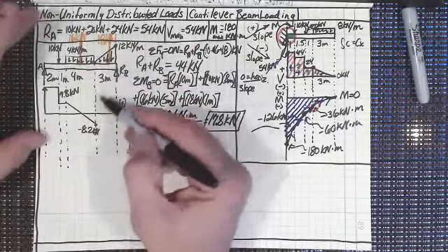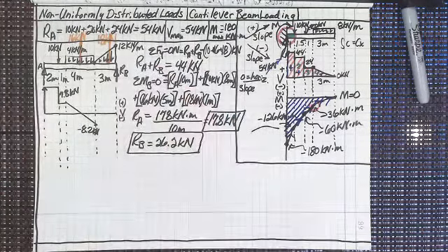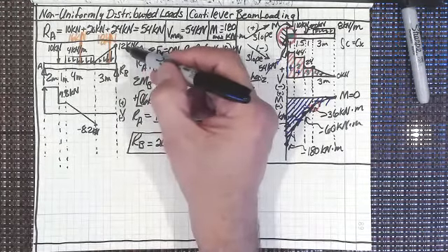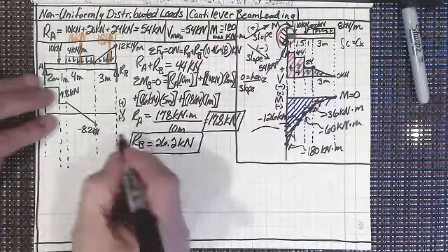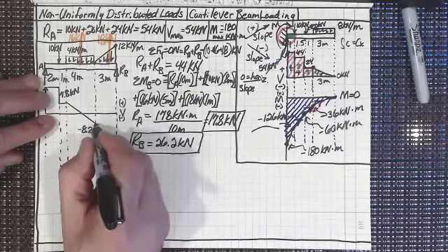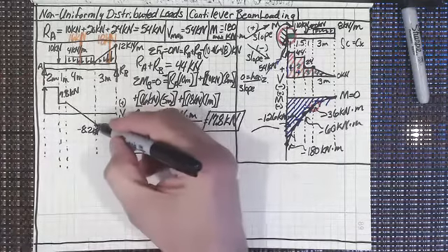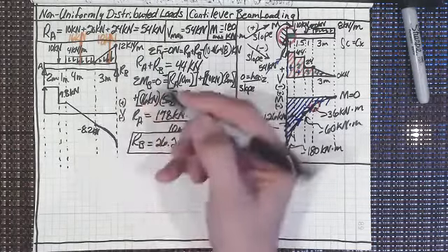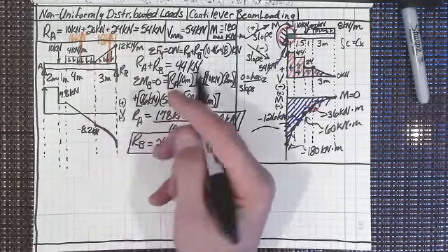So the slope is going to go from 0, and then it's going to go to a higher positive number. Is it going to go vertical? Is that infinity? No, it's not infinity. So it's going to go to a maximum of 12 kilonewton meters per meter, right? So it's not going to infinity, but it is going to look like this, right? Because it's parabolic. So it keeps this, but then it falls down there.